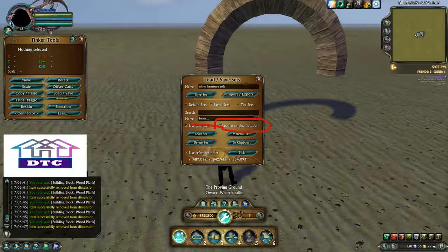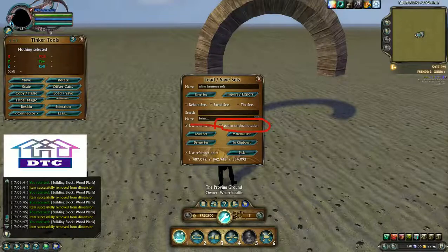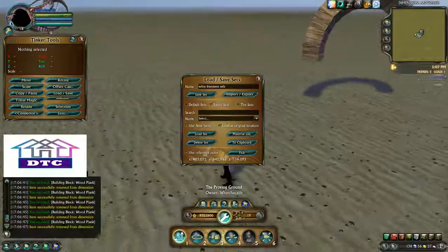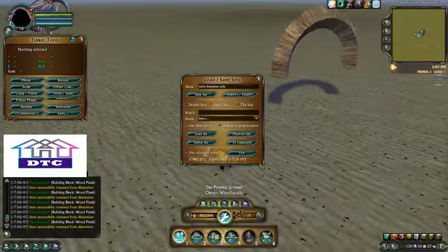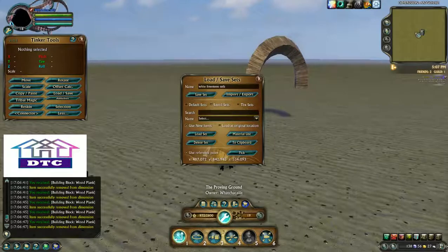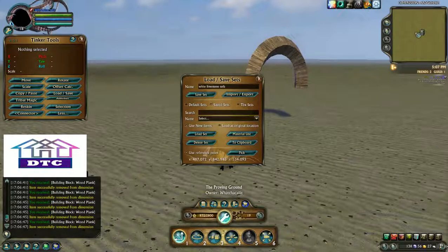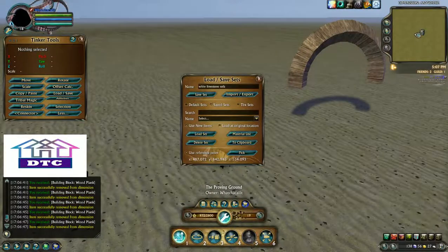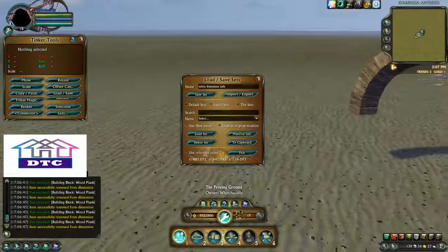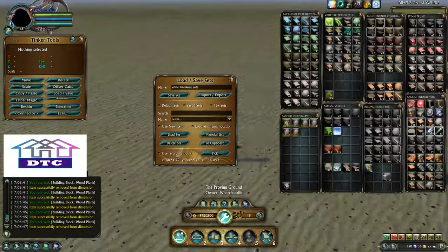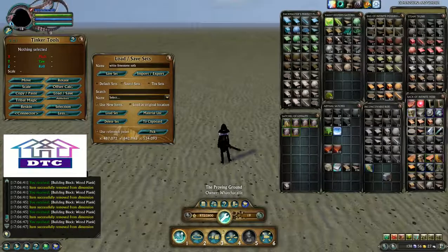If I say I made the couch here, but I want to use it in say Methosian Cascades in a house I'm building there, it's not going to work. Loaded original location, it should throw up an error that says this location is 800 and some meters from where you currently are. Do you still want to load? Answer is going to be no. So I'm not usually in the habit of even using the loaded original location.